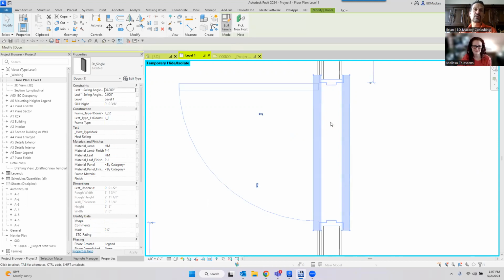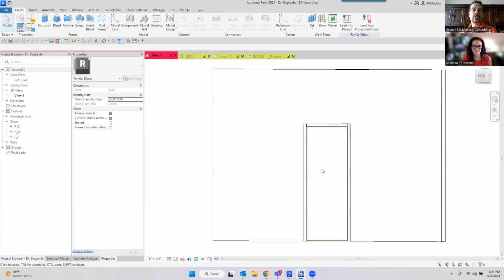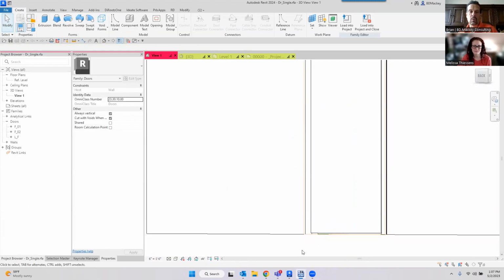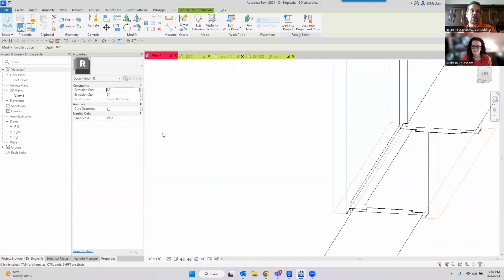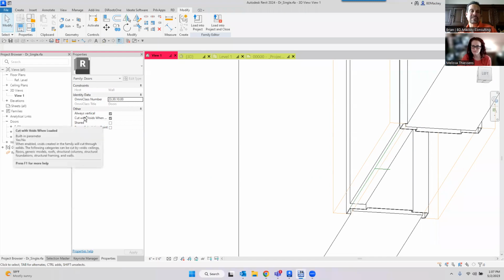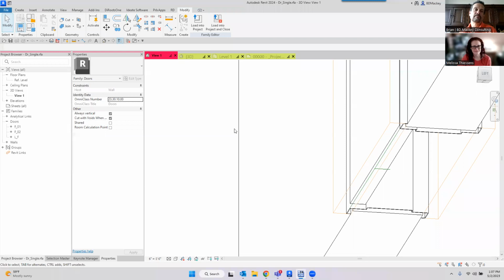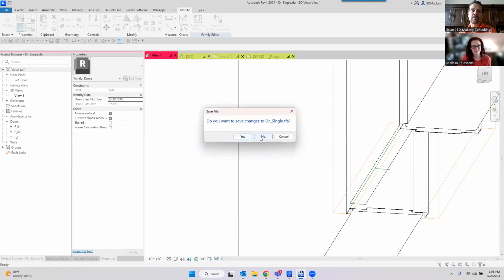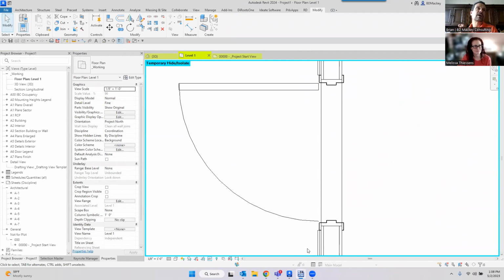Unfortunately, I didn't find a way to do it. I didn't spend a ton of time researching it, because the way this was done is I just put void families in the door that aren't cutting anything. So you can see there's a void family front and back in this door. And then in the family itself, I just have cuts with void when loaded checkbox checked. So that's all I got. That was it, just a question for you guys. If you want to think about it, respond in the chat at some point saying yes or no to the door voids. Not sure what you guys think.